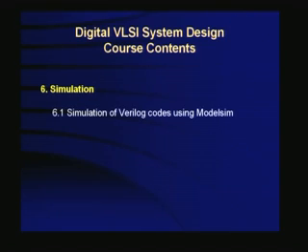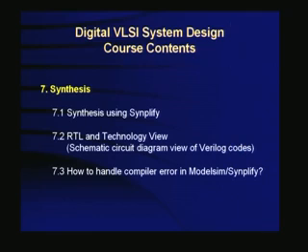And then we will simulate. First of all, we will have to simulate it before you plunge into the fabrication. So for simulation of Verilog, there is a tool called ModelSim, which will be used along with Verilog, and we will tell you how to use it. And then you have to synthesize it. Synthesis is actually building the design block by block, component by component. This is where the behavior description is translated, after the simulation of the behavior description or the Verilog simulation. You have to synthesize it, which is ready for implementation, mapping onto the FPGA.